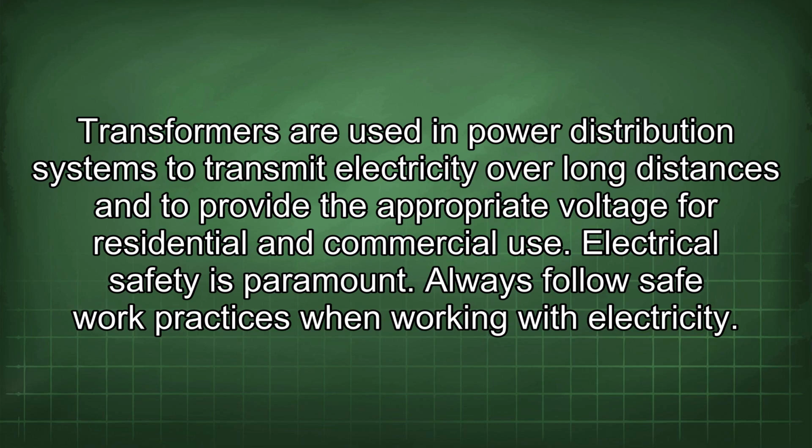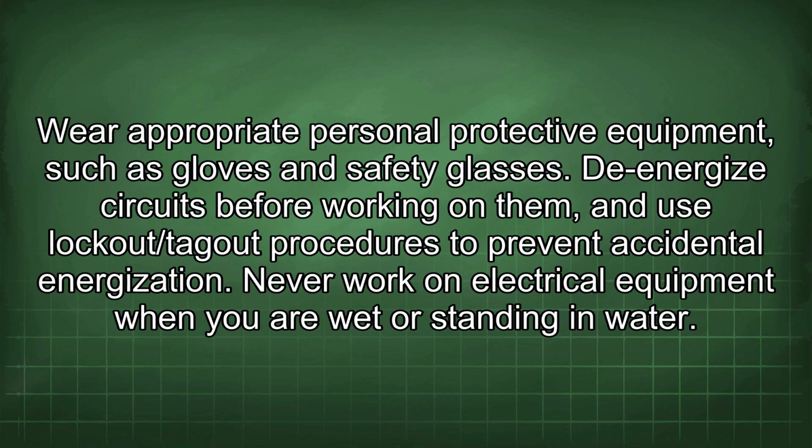Always follow safe work practices when working with electricity. Wear appropriate personal protective equipment, such as gloves and safety glasses. De-energize circuits before working on them, and use lockout/tagout procedures to prevent accidental energization. Never work on electrical equipment when you are wet or standing in water.